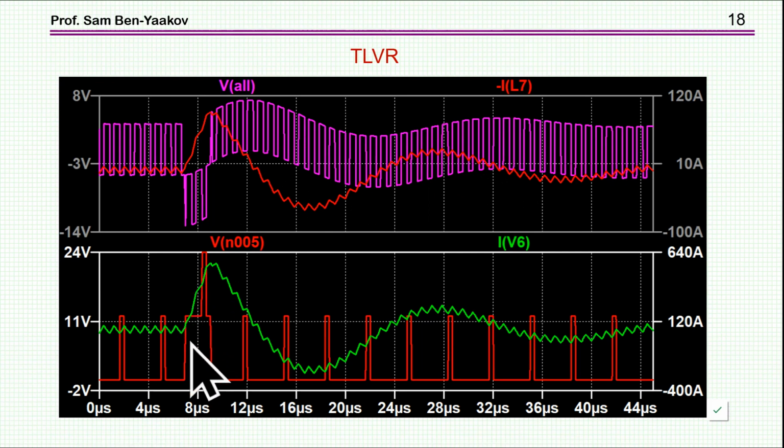So this change here, this pulse is reflected as a change in the voltage of the secondary. This is the total voltage, all the total voltage. This change is causing a current change in the secondary. This current change is now reflected to all the primaries, and now this is now the total current coming out of all of the inductors or the coupled inductor into the load. Okay, now I'm showing here one pulse, and there is a transient here.